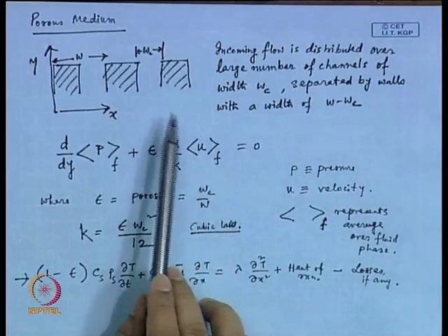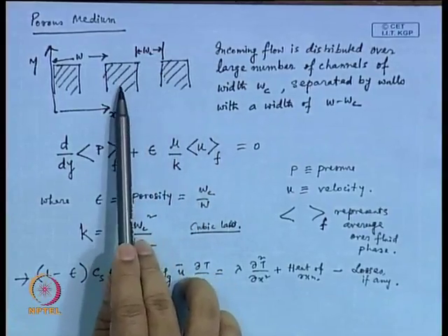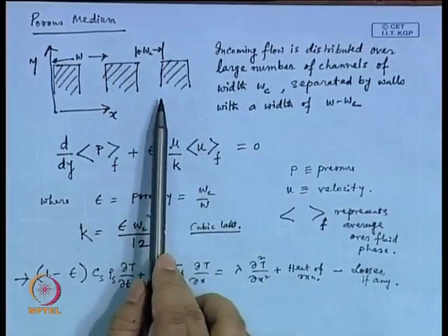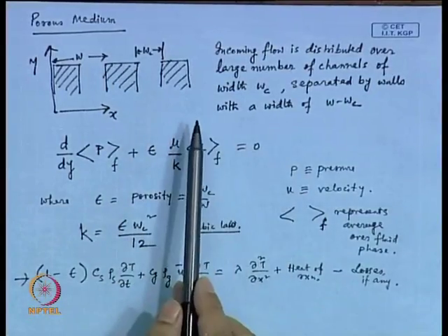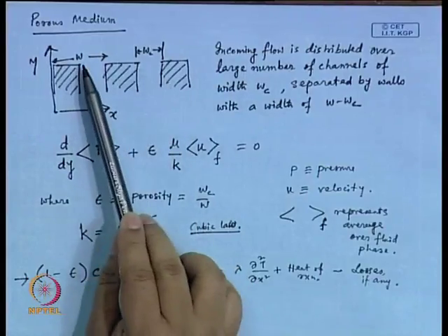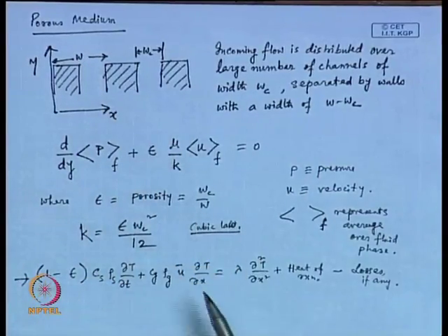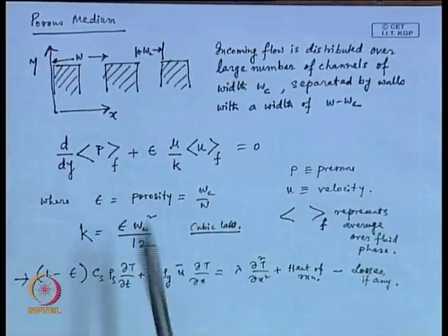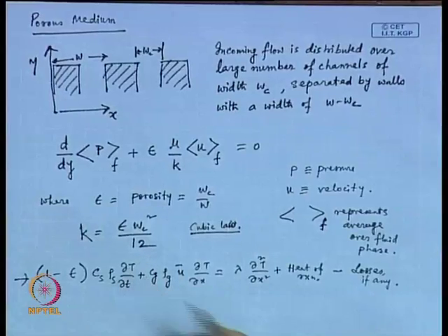I am talking about a monolith, where some portions are solid material, then I have a coating of catalyst on the wall which is helping me achieve the conversion that I want, and I have a flow going on through these channels. Whose temperature is this now, and how are we writing this? That lies in the assumption. You are treating these as if it is a single medium and it has a temperature, as a function of time, and as a function of x I can see.